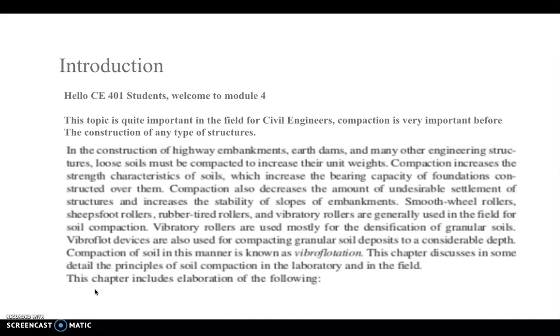So basically, we want to reduce the voids within the soil, because those voids are filled up with air or water. So the process of compaction involves removing air from the soil particles without any significant change in the amount of water in the soil.